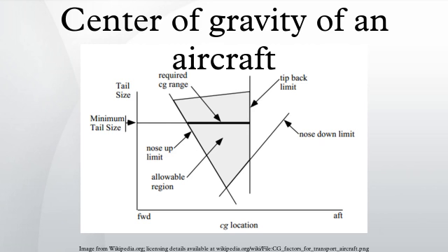The helicopter will have a tail-low attitude, and the pilot will need excessive forward displacement of cyclic control to maintain a hover in a no-wind condition. If there is a wind, the pilot needs even greater forward cyclic. If flight is continued in this condition, the pilot may find it impossible to fly in the upper allowable airspeed range due to inadequate forward cyclic authority to maintain a nose-low attitude.